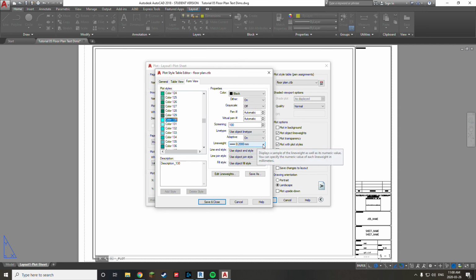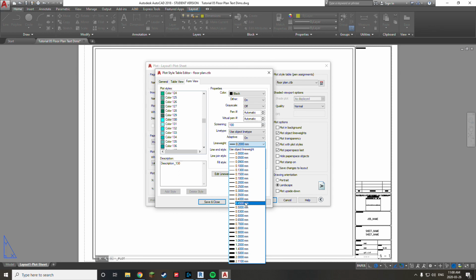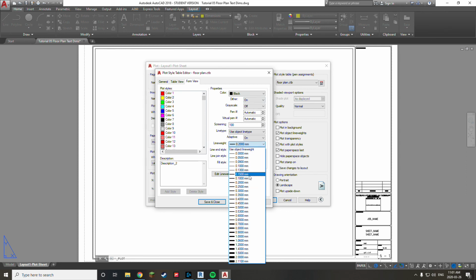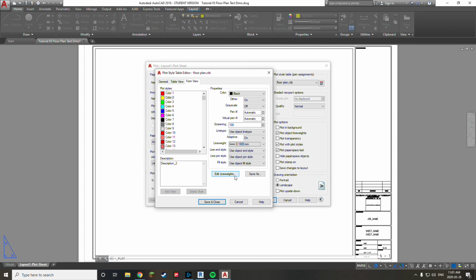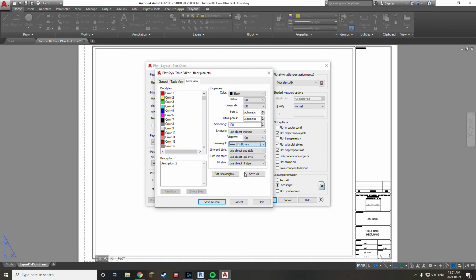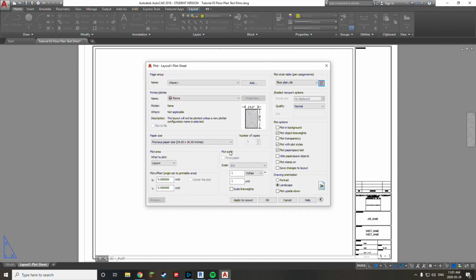I will change its line weight for my walls to be, let's say, decimal 5, because it's more dramatic and it's easier to see on my screen when we do a preview. The dimension color being color 2, let's say decimal 18. Sure. So I've only really changed two things. Most lines are medium line weight. I made the dimensions a little bit lighter. Let's go 1.15 actually.